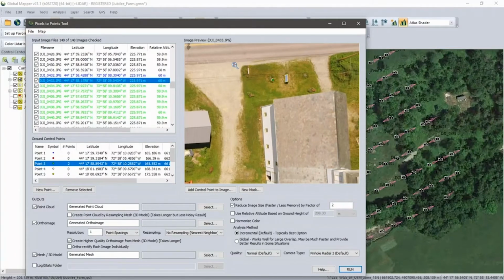A question about the requirement for ground control. In this example, the ground control didn't exist originally. In fact, what we're going to show you did not actually use ground control. These are fake ground control points, as I mentioned before. Ground control is not necessary for the process. What ground control will do, and if there's any surveyors among you there, I apologize, it will more accurately tag what we're going to output into the real world.